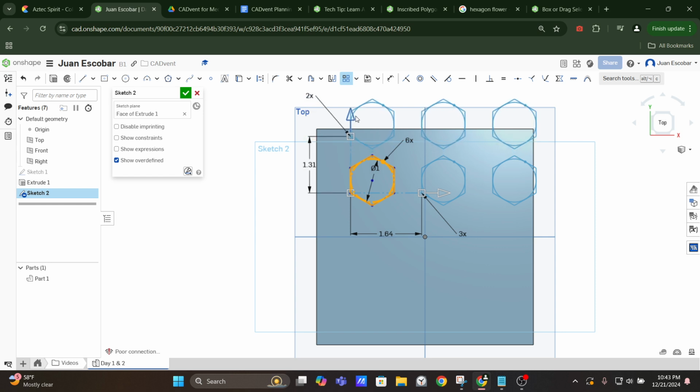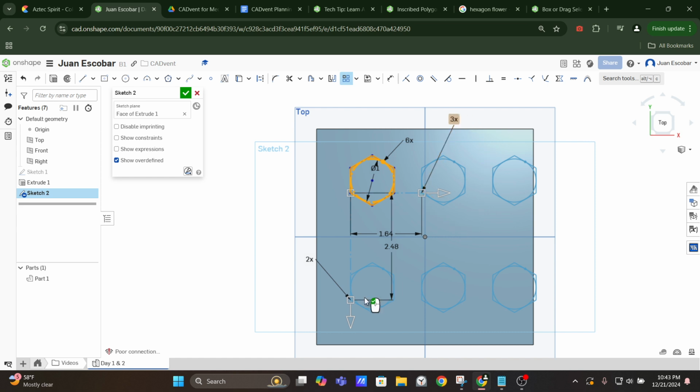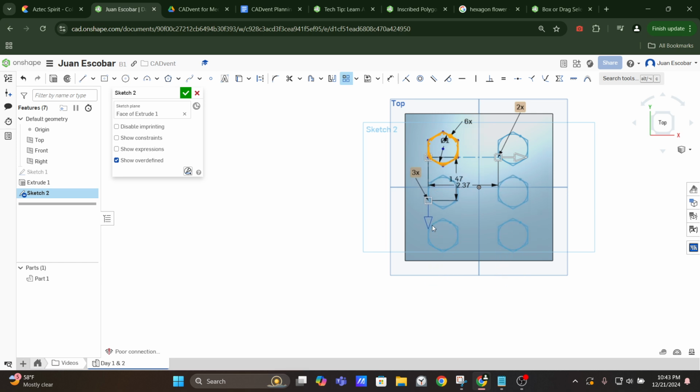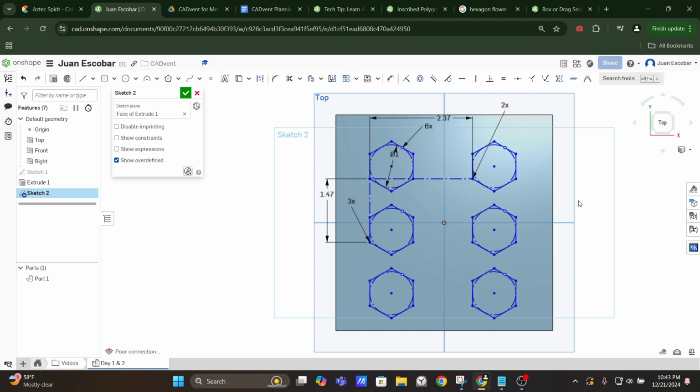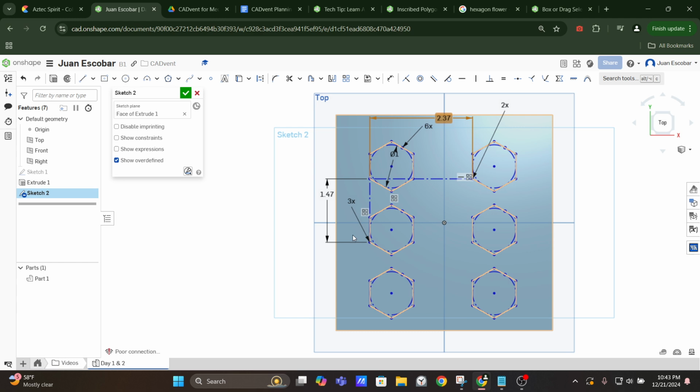If you drag on your other arrow, you can change the number of copies of your design that will be in both directions. Let's say I wanted it to be a 2 by 3. Think about it like a grid array type thing. It's really cool, and pretty handy. Yesterday, if you guys were making a ton of circles by hand, that's awesome. But if not, here's another tool that you can know how to use. And then to confirm your pattern, you just left click, and then it makes some dimensions for you.